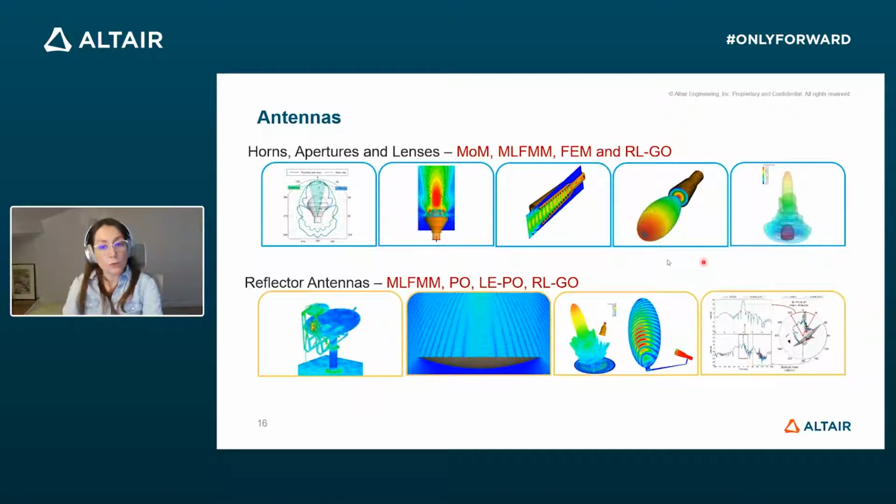But also, if you have more complex and more detailed antennas, or even electrically bigger antennas, you also have the possibility to model them and to start using some asymptotic solvers depending on the element size in your geometries, etc. And the bigger we go in the electrical size, the more interesting becomes the use of the asymptotic methods, such as the physical optics and the ray launching optics.